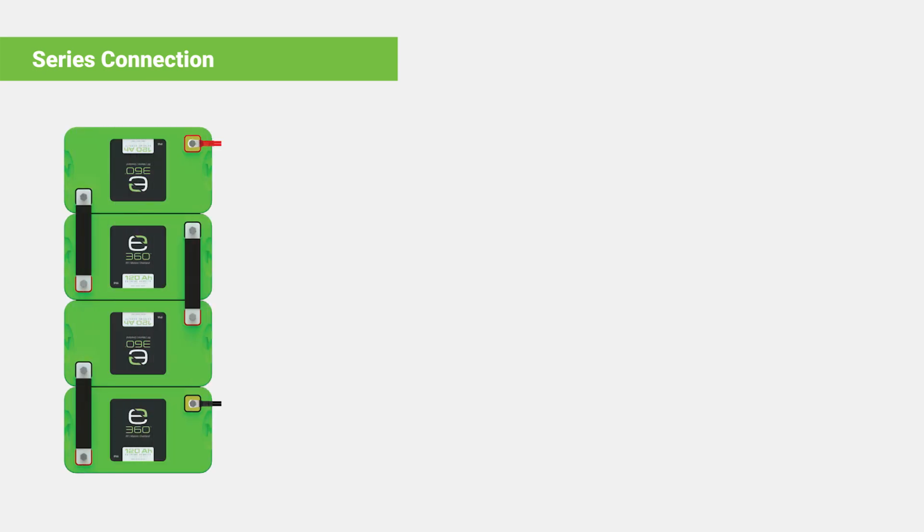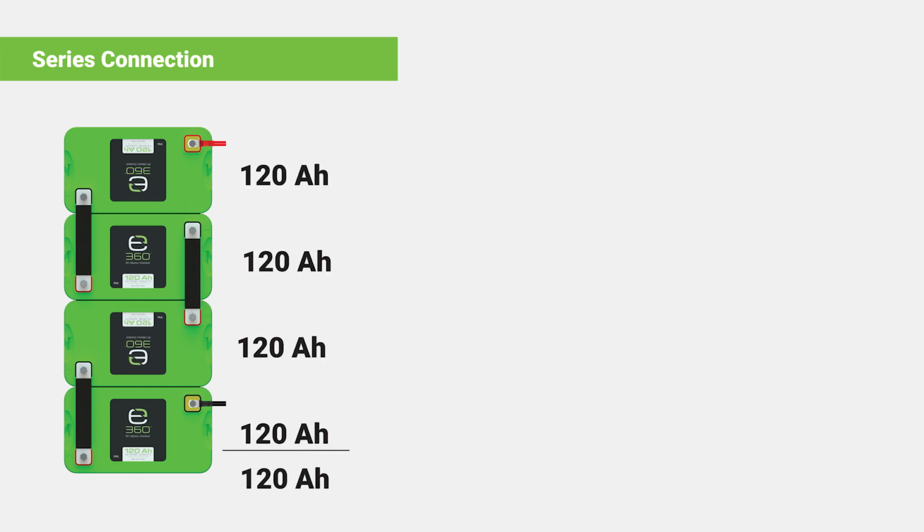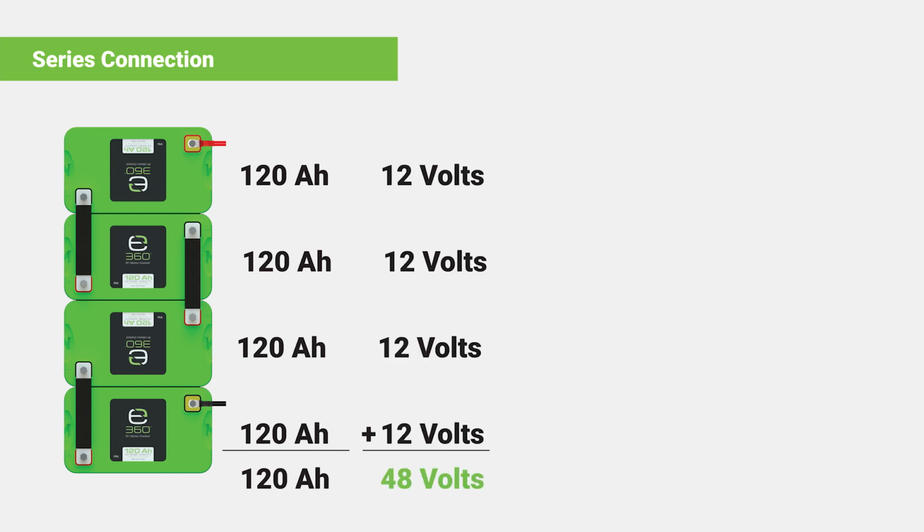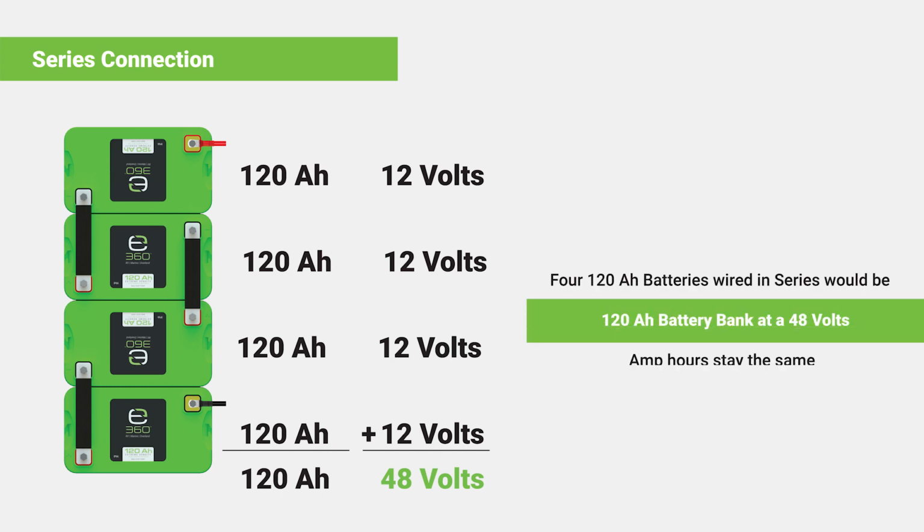When wiring batteries in a series, the following effects will take place. The energy measured in watt-hours will increase incrementally by the amount held in each battery. The capacity measured in amp-hours will remain the same as the rating of the individual battery. The voltage measured in volts DC will increase incrementally by the rating of the individual battery. The current measured in amps will maintain charge or discharge rates by the amount held in an individual battery.